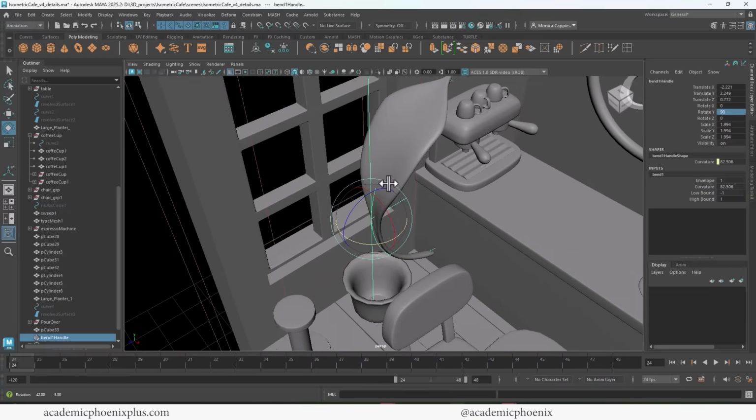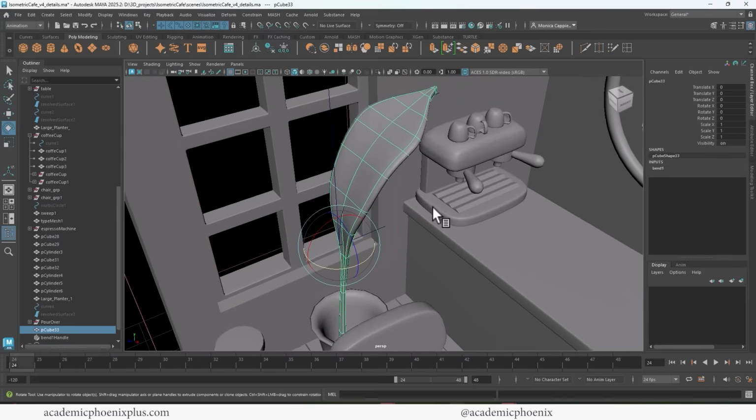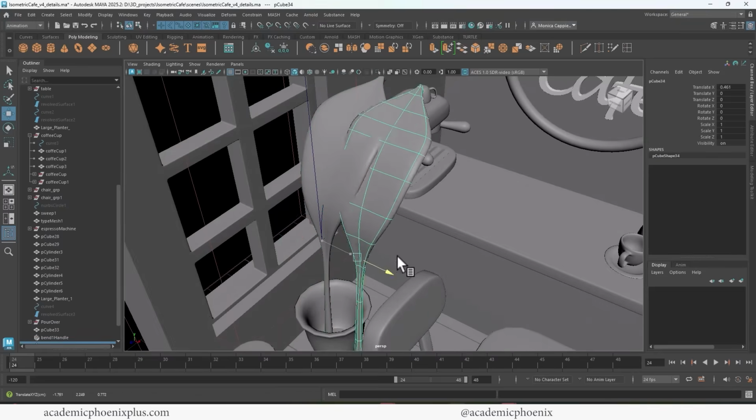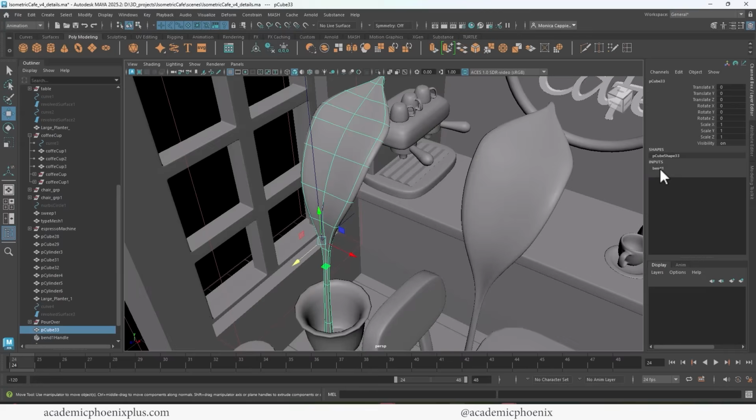Like so, but it also is bending the bottom portion, which I don't want. So that is the low bound. The low bound, if you change that to 0, you now have a bend a leaf. Now, if I want to make different types of curls, then I would say duplicate this one, right? So it's permanent. I'm going to nudge it to the side, and then I can go in, grab the bend deformer, and maybe I want to bend it even further.